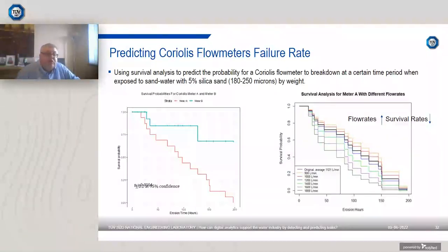By applying these new modelling techniques to a data set that until now had resided on a server unopened for 5 years, we've extracted new information relating to the performance of the meters. We've provided a means of predicting flow meter life expectancy in harsh environments without the need for removing and inspecting the meter by hand. Furthermore, by analysing correlations between diagnostic data values, it is possible to determine the concentration of sand within a flow system, essentially creating a sand flow measurement meter. Such diagnostic tools are becoming ever more critical to production and metering operations, where reduced downtime and overall costs are a key focus for the end user.